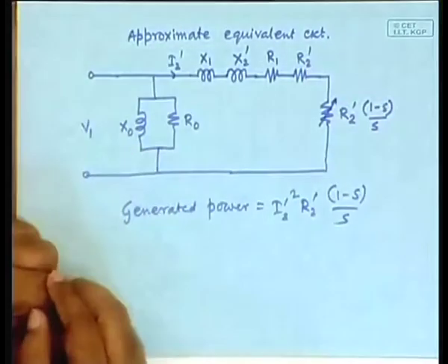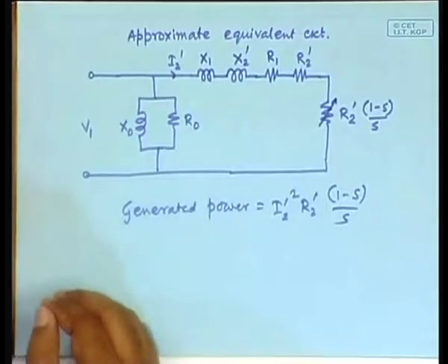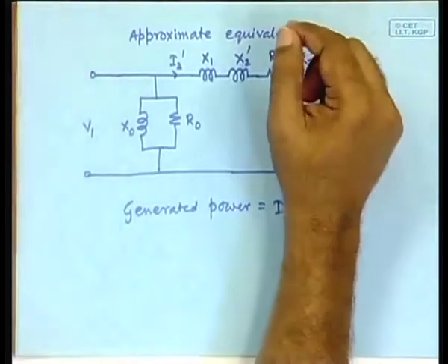If you have a wind farm or a large number of wind turbine generators at one place, it is usual practice to place a big capacitor at that spot, so that the reactive power is generated right there, and that is what gives the reactive power into this supply. The reactive power does not have to come from the actual transmission line, because if it has to be drawn from the line, even though you are not drawing active power, it pushes up the current that goes to the line. If it pushes up the current, the I square R loss, that is the transmission and distribution loss of the line, will also go up, and so it is desirable to have a capacitor at the end, at the terminus here.